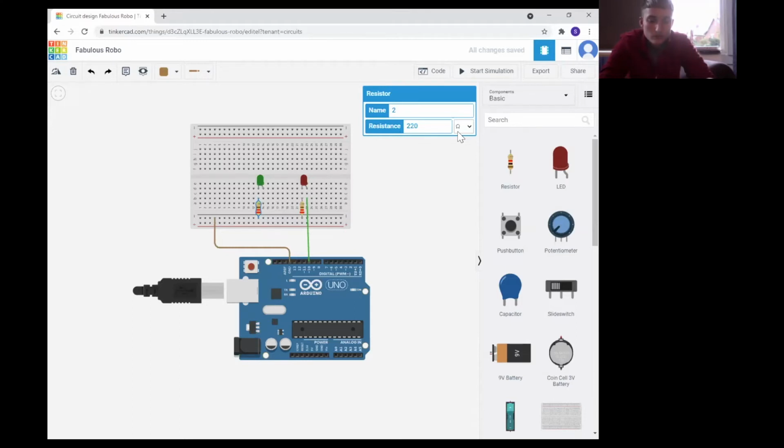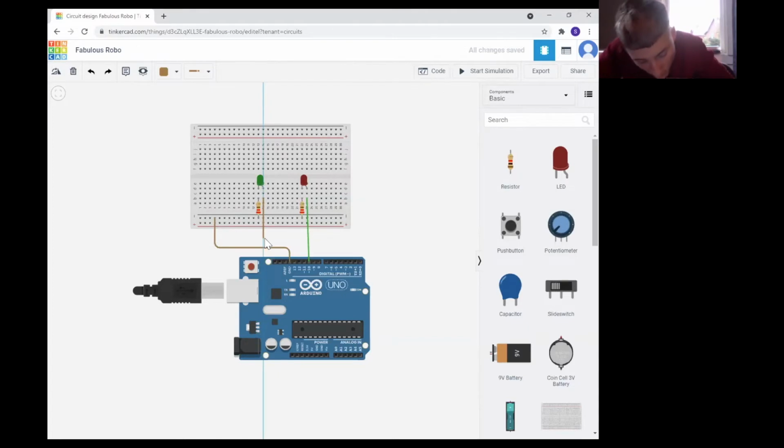All right, I'm going to add one more wire before handing back to CJ to make the real, the physical circuit. Now, you'll see that this isn't quite the same as this circuit, is it? So we want to connect the LED to a different pin on the Arduino so that we can control it and send it instructions. So I'm going to create another wire that goes from the other leg of the LED all the way down to pin 11. Like that. And I'm going to make that wire green as well, just so that it matches.